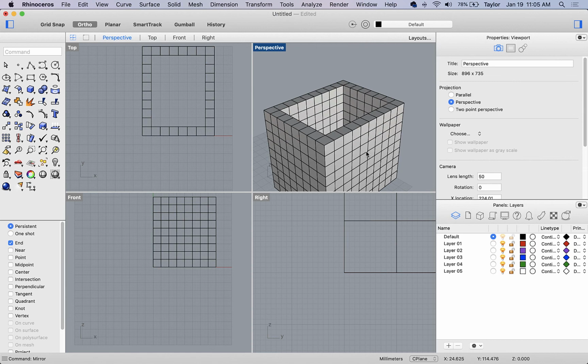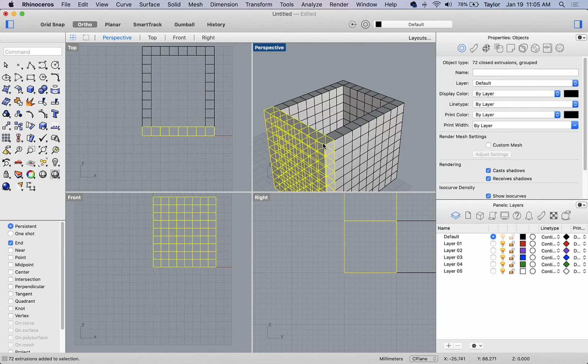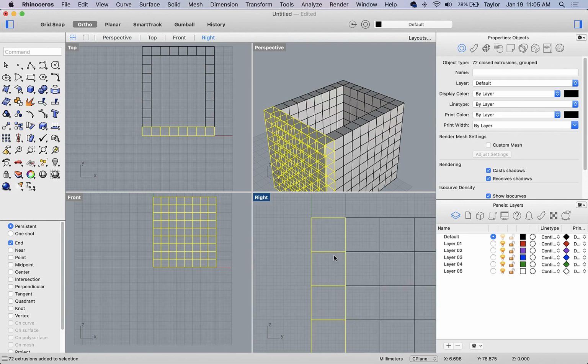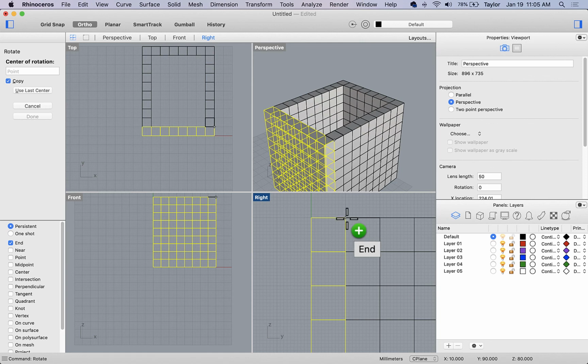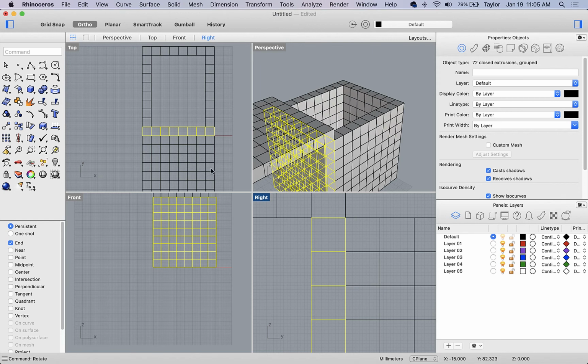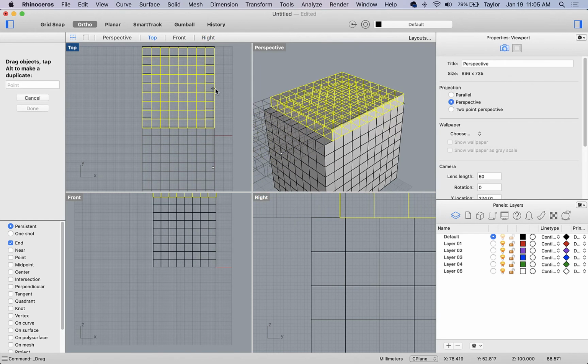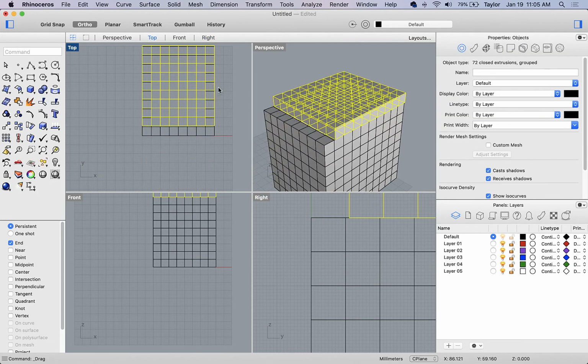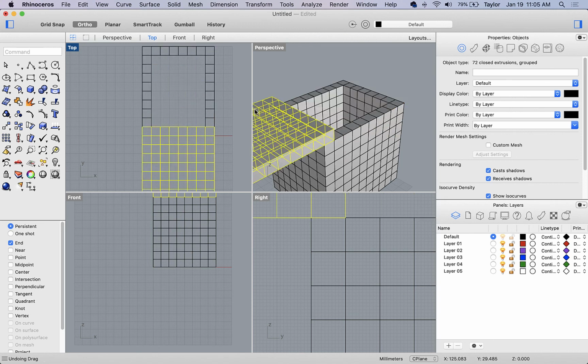If you wanted to, you could take one of these walls and then rotate it up for the ceiling. So here I can move into a different viewport and say rotate. And so here I'll do axis of rotation, point number 1, point number 2, and left click and then enter. And now I'll just have to take this and then sort of move it into place. You can see me trying to casually put it into place, which is not working because snap is not selected.